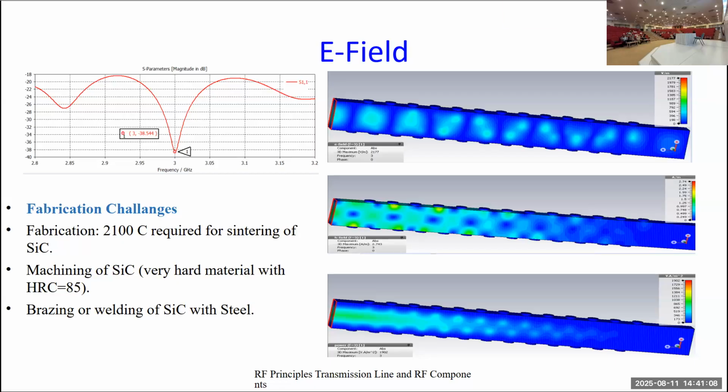Here we have shown scattering parameters. These scattering parameters, called S11, which I have plotted here, tell us how much power is absorbed in the cavity. If this is the resonant cavity, the scattering parameter will be very, very small. Here it is given in dBs. And if it is not resonant, as in this case, it will be a little higher than that.